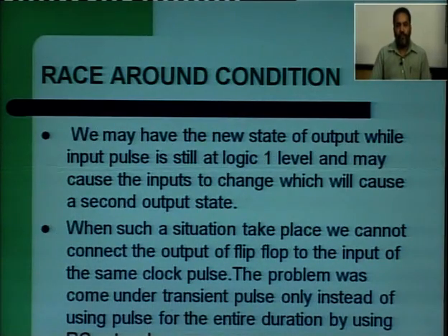We may have the new state of output while the input pulse is still at logic 1, that is, still in that period only. While the input pulse is at logic 1, the flip flop changes to its new state, and this may cause the inputs to change.